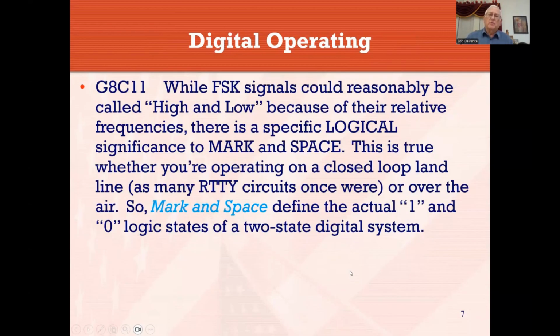Okay, FSK, frequency shift keying signals, can be called high or low or 1 and 0 in the digital world. For this particular purpose, we use the terms mark and space instead. And again, that comes back from the old teletype world. Mark is a 1, and space is a 0. On the landlines where teletypes were connected together, the old teletype would be sitting there just going chunky, chunky, chunky, doing spaces. It wasn't receiving anything. It was just marking time, literally.